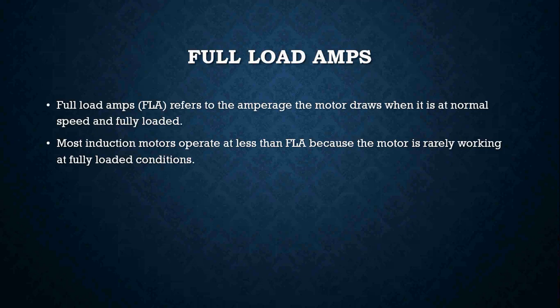When we are troubleshooting a motor and we're taking amperages, we want to make sure that the motor is operating at less than the full load amps. If it is operating at a higher amperage than what it's rated for, there's probably a chance that the windings inside the motor are starting to break down, and eventually the motor is going to fail. Okay, it's something that you may want to note on a service slip, or let the homeowner know that it is running a little high on its amperage.